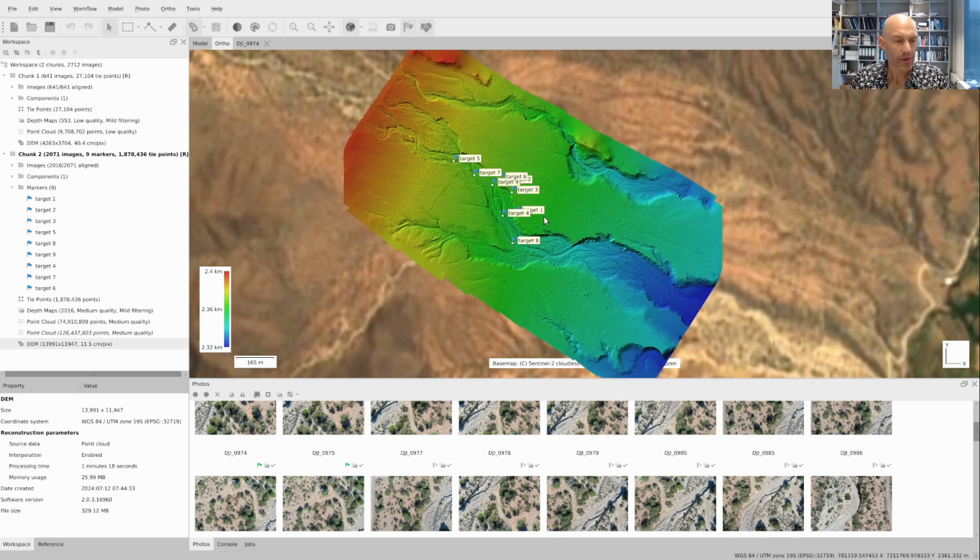Okay, with this I hope that I could show you some relevant steps for georeferencing your data and also performing a careful camera calibration by using these targets. I showed you some quick filtering steps that allow you to reduce the data density of the point cloud, remove some of the vegetation, perform a very simple ground classification, and generate a first order digital elevation model.